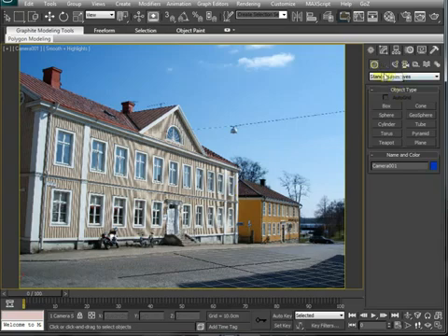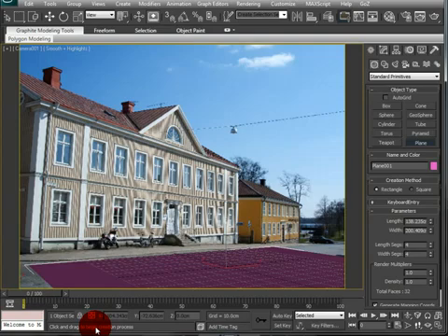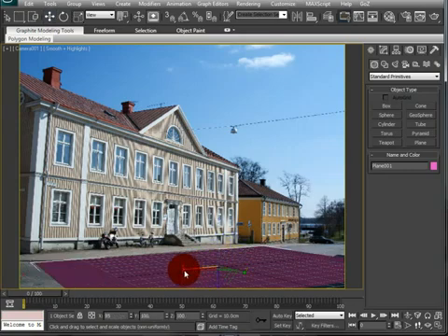Okay, let's drag out some geometry now. I'm going to drag out a floor plane, so in the Create tab, I'm going to click on Plane and just drag a plane out. That'll do. Now you can press W to select the Move tool and just move that into place if you want, and you can use R, which is the Scale tool, to just alter the basic dimensions of it.